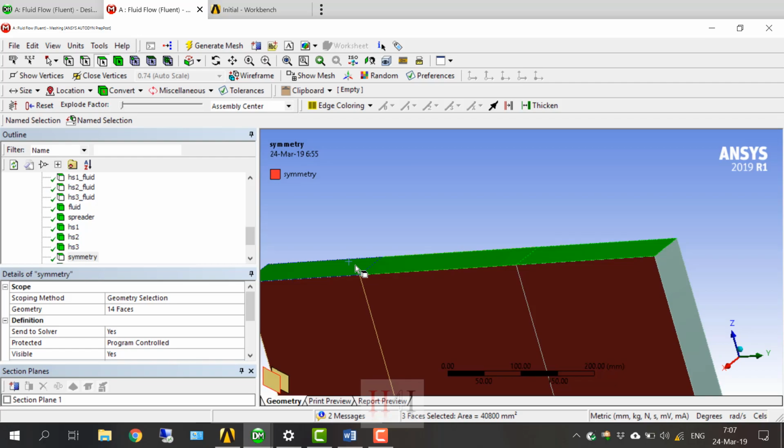And if you are afraid of some flow in this area, you can define it as a slip wall, a wall with shear equals 0. So if there is flow, it doesn't affect it by the wall. But the best solution, of course, is to define an equation. If you don't have the latest version, you will not define an equation except by UDF.